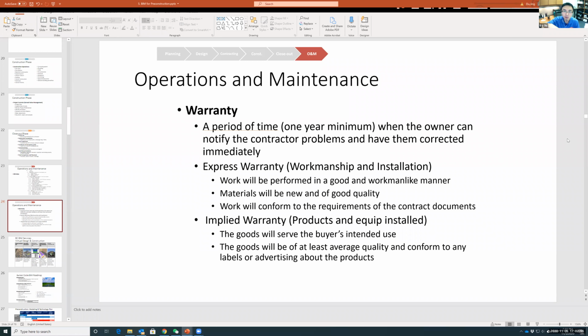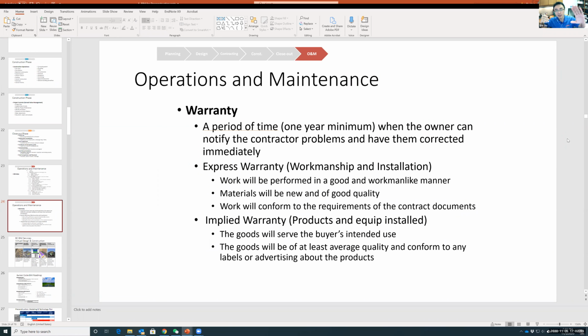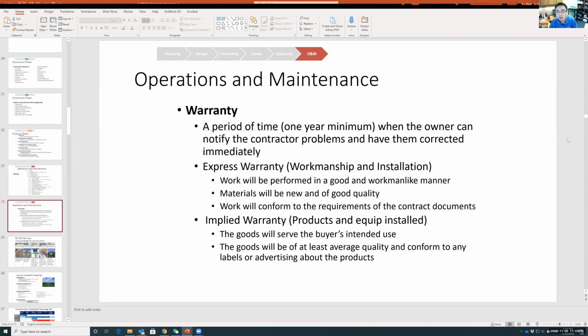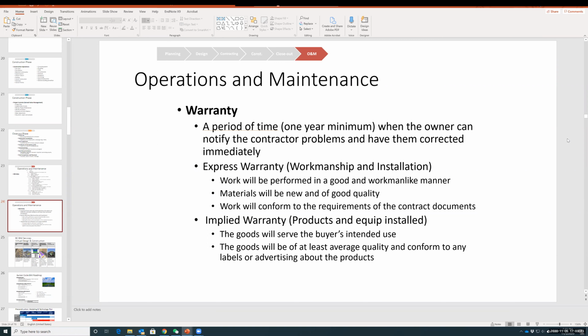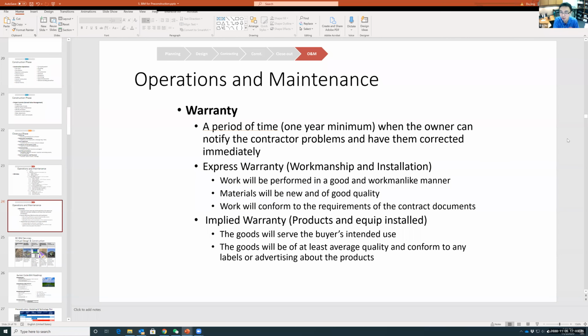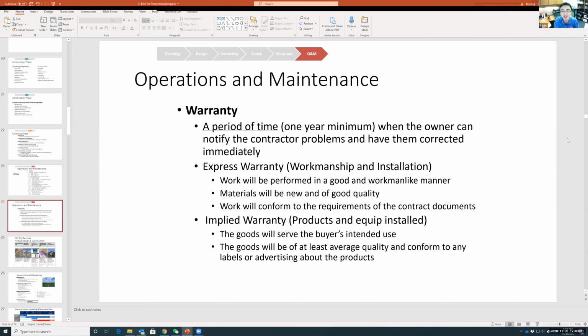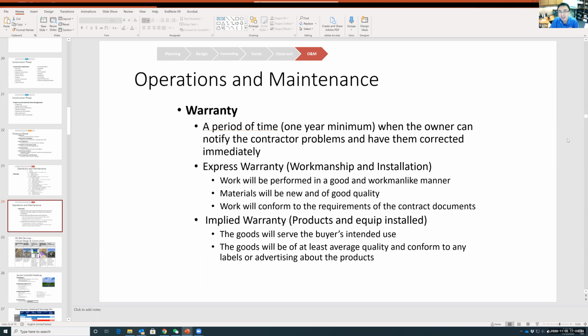And they basically tear down the wall, and they saw there's a nail from the drywall. The nail is supposed to fasten the drywall, going into the main water supply line, and put a small hole there, and after 20 years that water supply line just exploded. So question one, is that a workmanship problem or product problem? Workmanship. So you guys know it's nothing wrong with the drywall. It's nothing wrong with the water supply line. Somebody from the construction company put the nail in the wrong way, right?